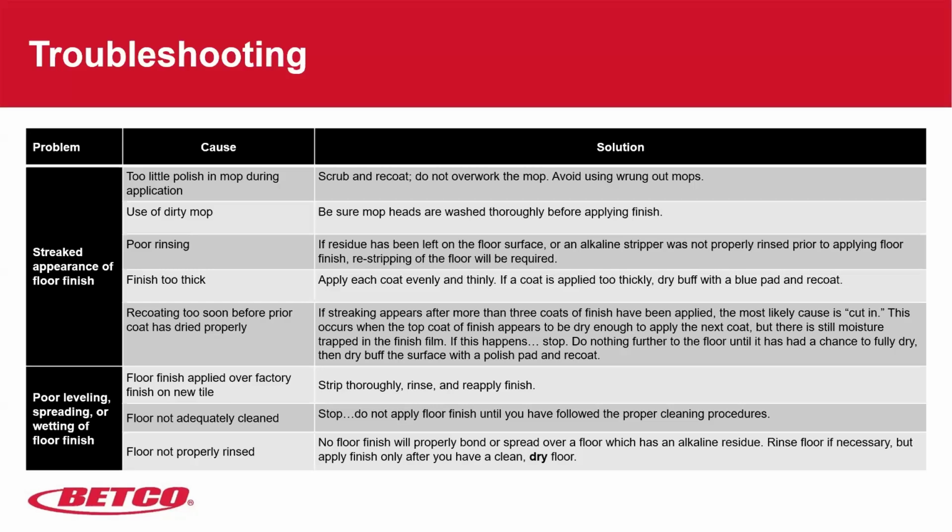I think we all know that floor finish dries from the top down. So it may feel dry to the touch. You may walk on it and not see your footprint, but as soon as you put another coat on it, you're liquefying that initial coat or the coats below, plus the coat you have on, and it's going to take a lot more time to dry and cure. So we don't want to rush it too fast, and we don't want to put it down too thin either.